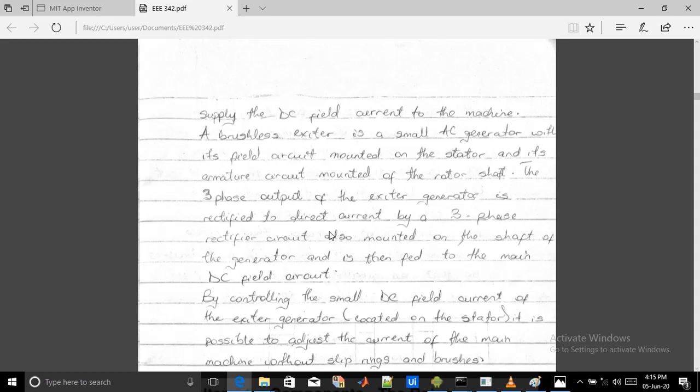is in the form of rotation. You get? So the rotation is what will aid the three phase that we are going to get. For rotation to take place, you don't have to find another means to make rotation take place, since the shaft of the main machine is rotating. Since the shaft of the main machine is rotating, you just use that to rotate the three-phase rectifier circuit.